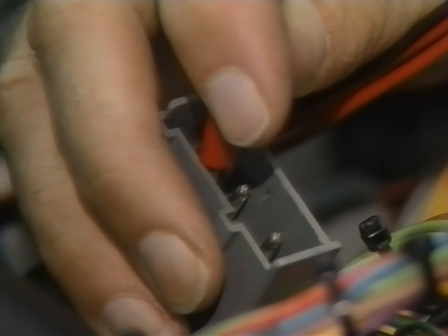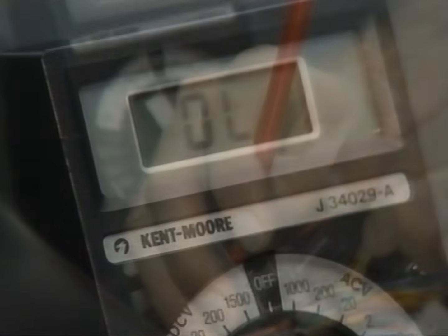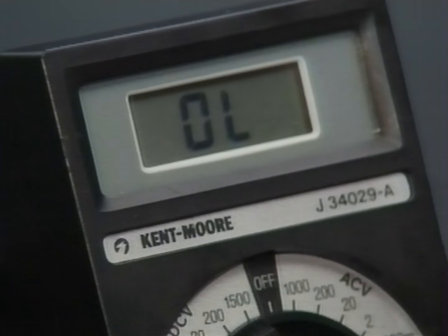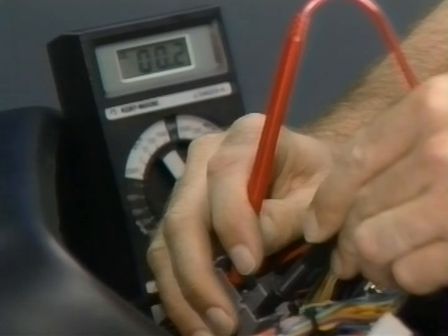Then check the resistance between pins A3 and A6 on connector A. If the resistance is greater than 10 ohms, there is an open in the circuit between connector A and the fuel level sender connector. You'll need to track the open down and repair the wire. If, with the sender wire grounded, the resistance reading between A3 and A6 is less than 10 ohms, it indicates either a bad connection at the connector or a concern in the EIP central display module.